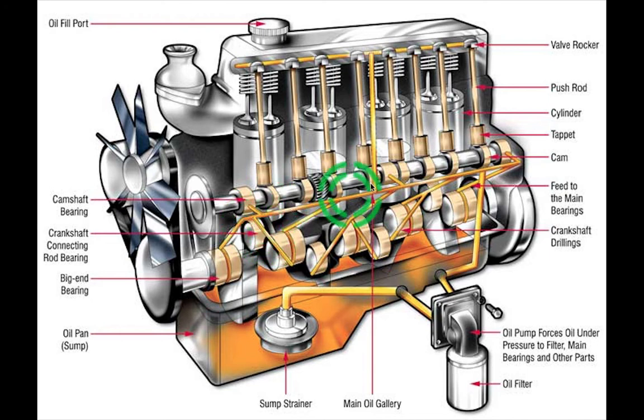Then the same thing goes and feeds the camshaft, whatever is in the rotating assembly. These are also in bearings and stuff like that, so they are also lubricated with oil. They are seated inside a film of oil, and they rotate in that. There is no metal to metal contact. And then there are other things which come in contact, like these lobes, these push rods, whatever that bucket thing is pushing over. So wherever there is metal to metal contact, there is oil between them, as simple as that. So oil is being supplied to that.